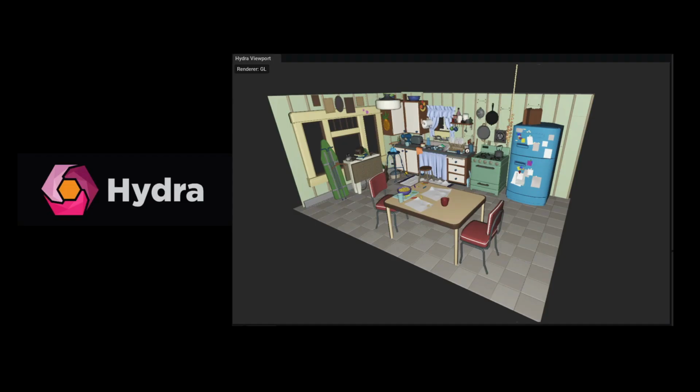But it's not just the RTX viewport that you can use. You can really use any viewport. At the core, we're leveraging Hydra, which is an abstraction on the viewport technology to communicate between USD and the various renderers. Leveraging Hydra and the Hydra viewport, you can bring different types of renderers into Kit and contribute to this ecosystem. Here in that screenshot, I show the HD Storm GL renderer that comes with Pixar.